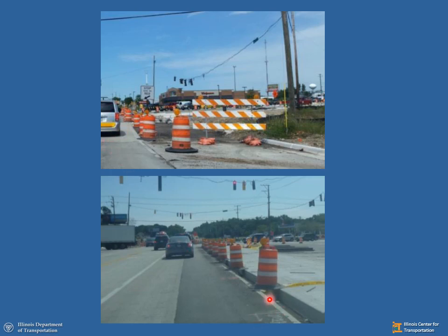This one's not so awesome because our traffic control devices are actually sitting right on the hazard. These barrels should at least be on this side of the hazard. Once they hit a barrel, it's all over. Their tire is stuck between the two different pavement structures, right?